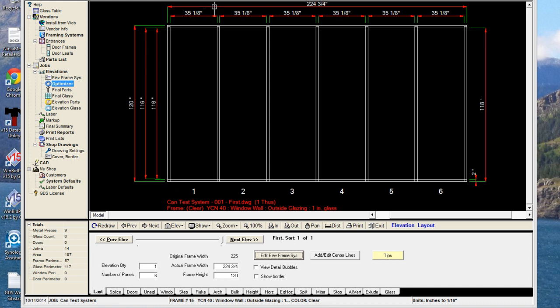But the reason there's overlap is because these verticals and jambs are extending into the cans. So it's fully extending into the sill can, and there's an inch left in the head can, basically. So it's showing us that, what you see is what you get, because we're getting longer cut lengths on these verticals.